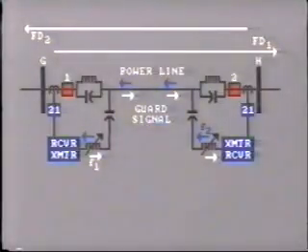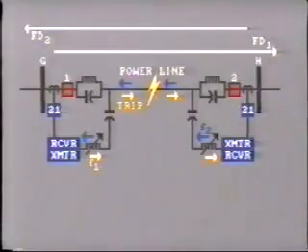Now, let's look at the case of an internal fault, let's say halfway along the line. At station G, the fault detector detects the fault and keys the transmitter to change frequency to the unblocked mode, so giving permission to the relay at station H to operate.